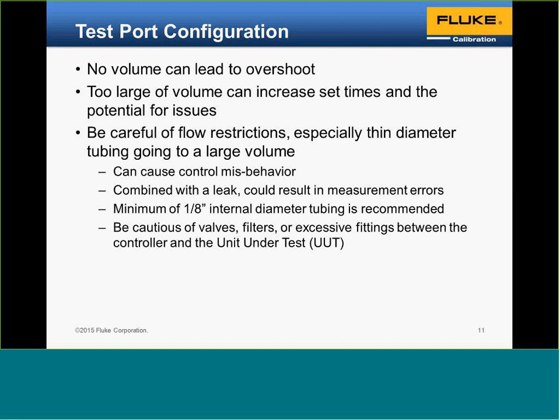It's very quick. You're letting in pressure quite a bit, and now you have the potential of going over the target and damaging the instrument. So have a relatively constant volume on the test port.